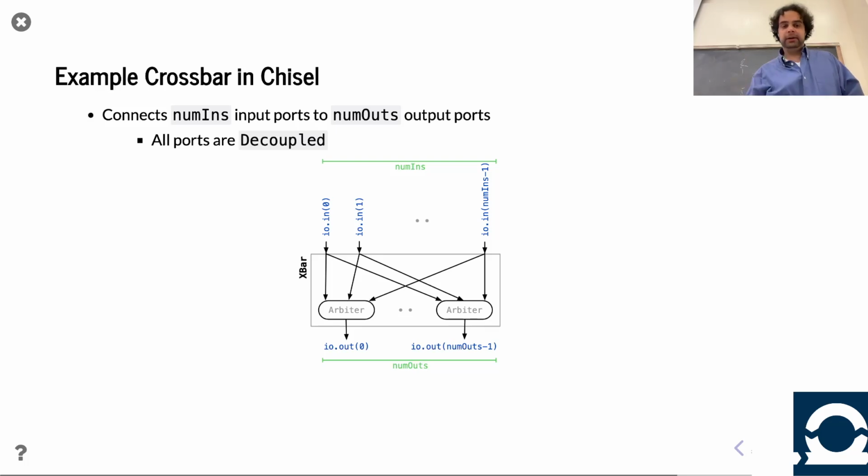So what we're going to do in our design, as you see in this drawing, is put an arbiter on every output port, and then just send wires from every input port to every arbiter for every output port. So there's a lot of wires internally, but in terms of actual logic, the logic is constrained to the arbiters for every output port. They convey progress or no progress. We're using decoupled everywhere, right? With ready and valid they communicate: yes, I have data to send, and the other end is going to respond. Are they actually receiving that data? Are they actually ready for it? Ready could mean the output itself is ready, or it could be that the output is ready, but someone else is requesting this port and they have higher precedence according to the arbiter, and you haven't won the grant.